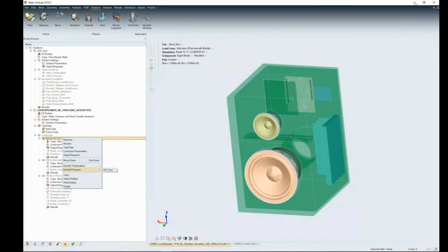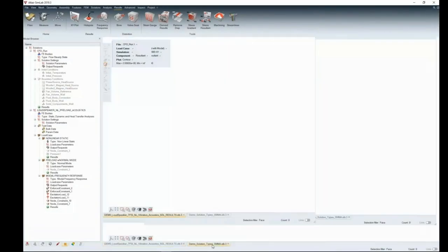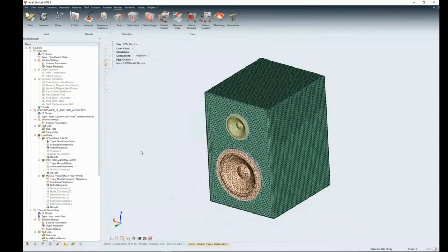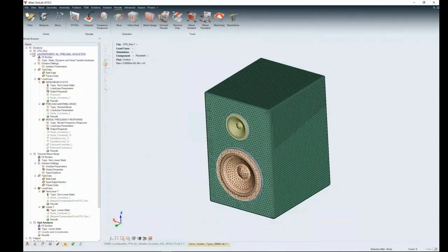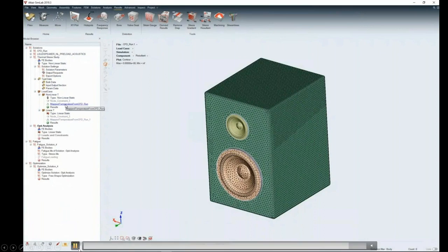These things are pretty nicely handled at the CAD level because you're dealing with a single common CAD. The only thing you're dealing with is a different mesh. Now, other than setting up a CFD and a structural analysis, you can also do a couple of other things which I raised in the first part in terms of key challenges. Irrespective of doing CFD and TFSI, you can also do a certain set of optimization analyses, or certain kinds of fatigue analysis in the same environment.